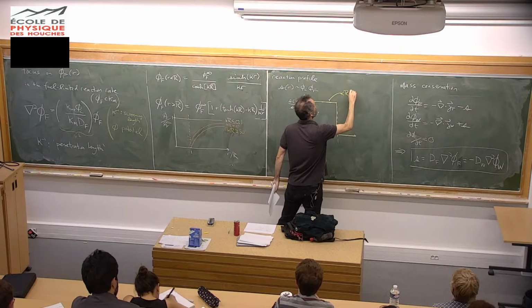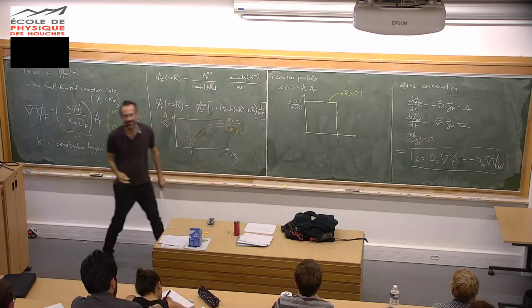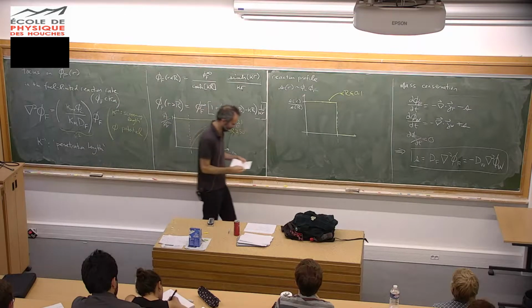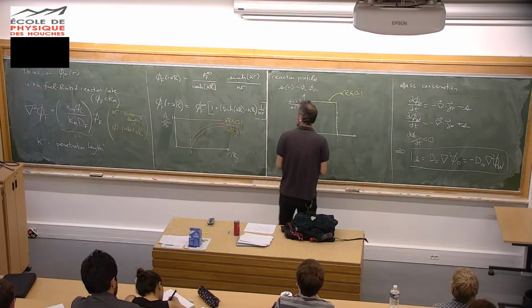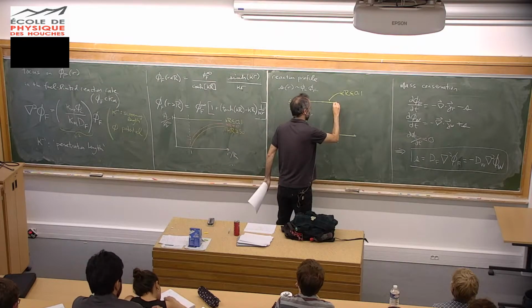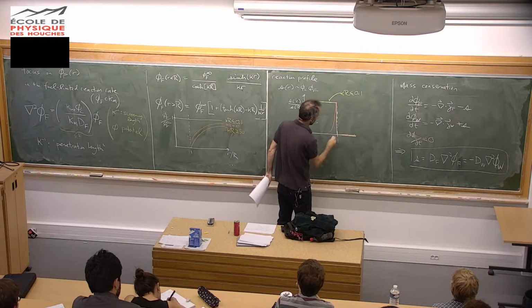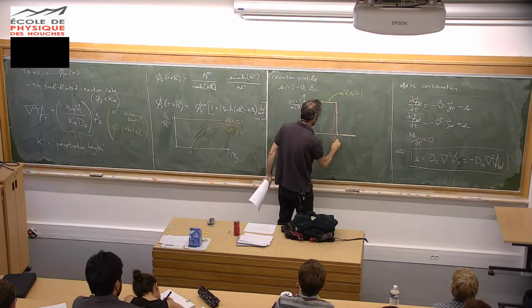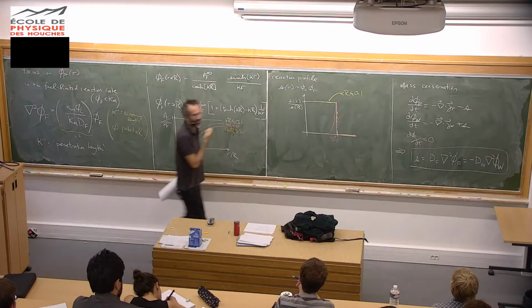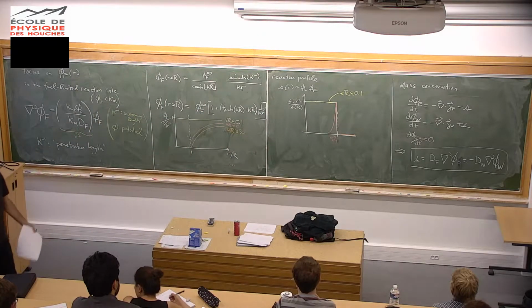If kappa R is less than or approximately 0.1, you have a perfectly uniform reaction rate inside, which is what we want if we want to make a material. And then if we have kappa R equal to 10, everything is localized over a very narrow band of kappa to the -1. So really all the reactions look like they're happening at the surface.